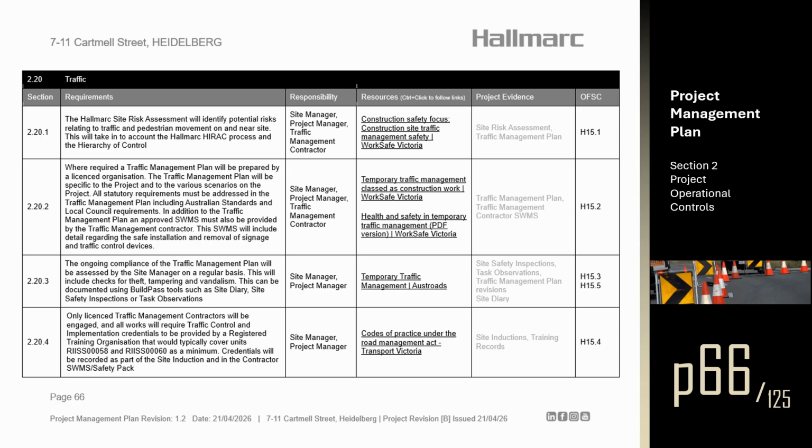All statutory requirements must be addressed in the traffic management plan, including Australian standards and local council requirements. In addition to the traffic management plan, an approved SWMS must also be provided by the traffic management contractor. This SWMS will include detail regarding the safe installation and removal of signage and traffic control devices.